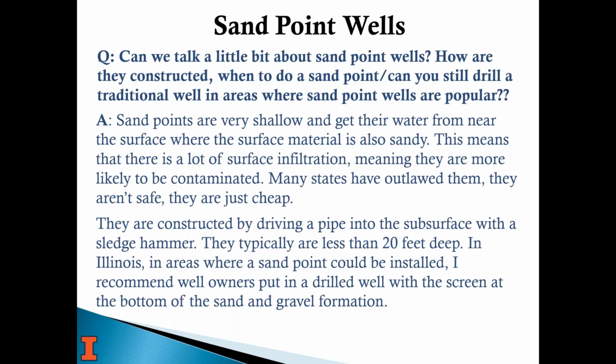A new sandpoint well is not allowed, but if it's already there, it's grandfathered in. People do this because it saves them a fair amount of money. The example I use is Mason County, Illinois. It's along the Illinois River. It's 120 feet of sand to bedrock, so the whole thing is the aquifer from surface on down, and the water table varies from 4 feet in some areas down to 40 feet.